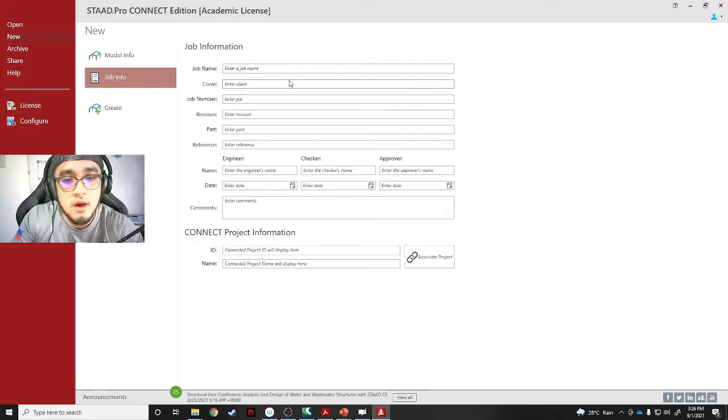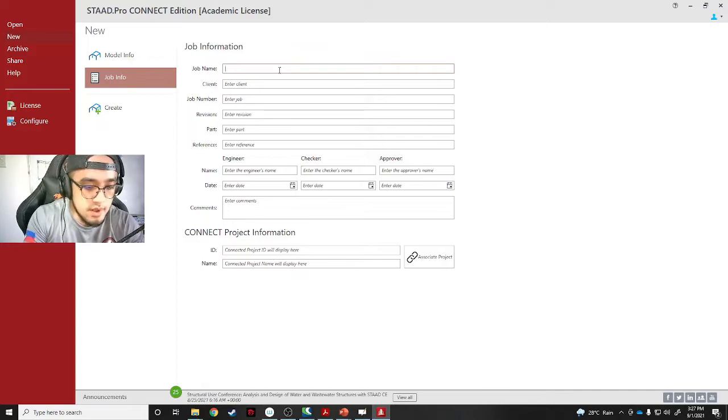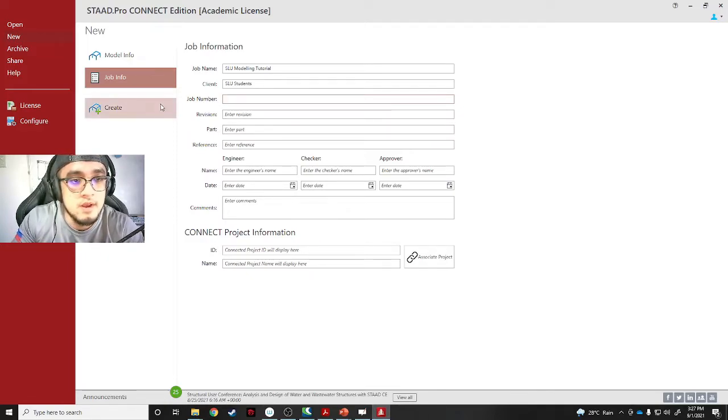So if you have your necessary details here, I mean, if you want to fill this up, it would be up to you. So let's say that our job name is to be SLU tutorial or SLU modeling tutorial. Just type them here. And for our client, let's say SLU students and whatsoever. So job number, it would be up to you to fill this up right here. So the next thing that you would be doing is to click create.